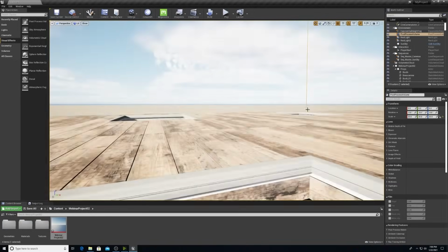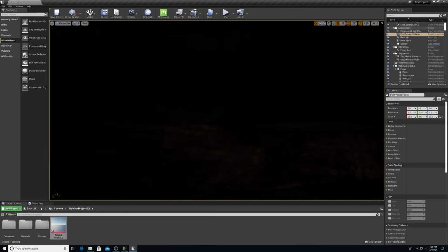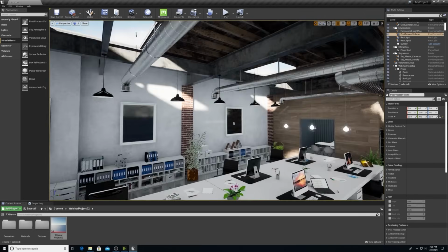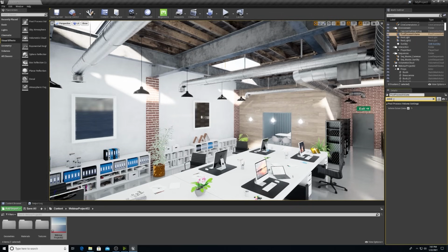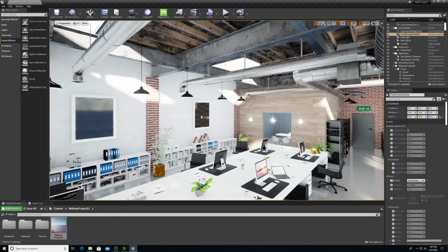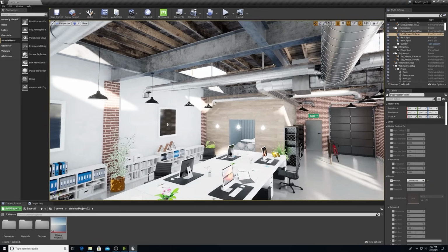So you'll see that when I come outside, I can see that box going around. Since this scene is just one large open space, I want the box to be unbound. To do this, I can go into the search details, type in extent, and make sure that this is enabled here. Now I'm going to clear out that extent, and I'm going to take a look at the auto exposure. I'm going to turn that off so that I can have consistent control and more realistic lighting throughout.